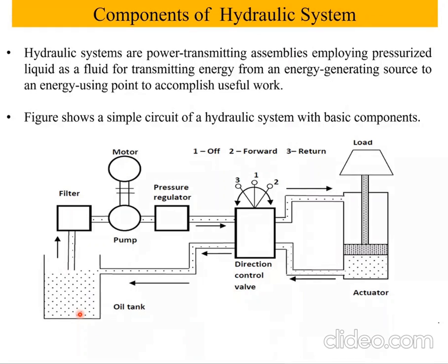After a certain period of time, if the oil in the tank gets disturbed, these settled particles will move up and get mixed with the oil, and they will start entering into the system. So there may be certain impurities, some suspended particles.